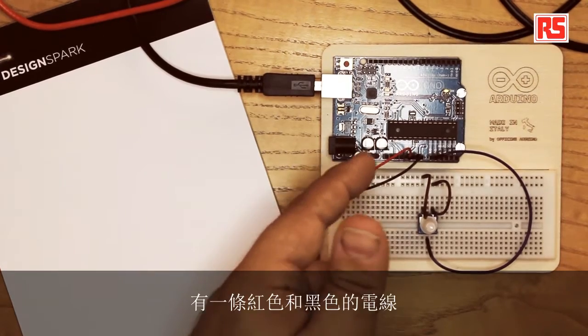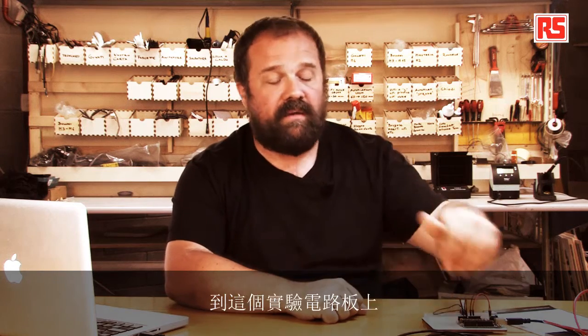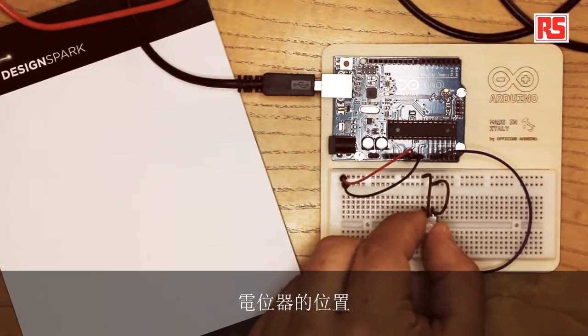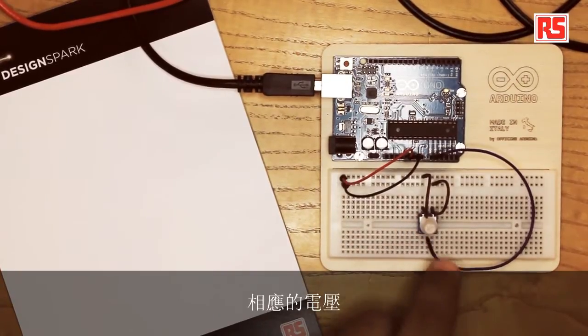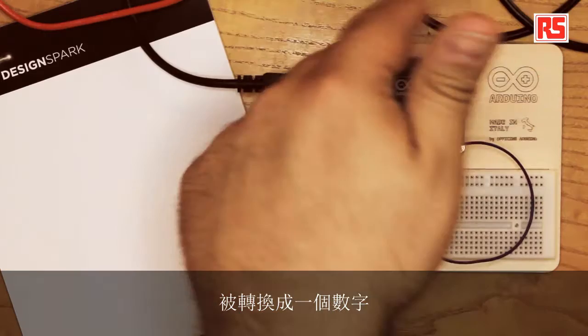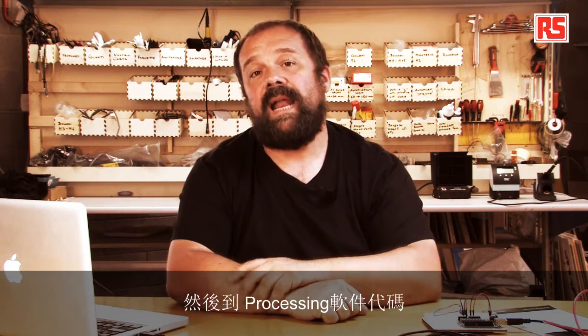And then we have a red and black wire going from those two rails to the 5-volt and ground signals on the board. So when I change the position of the potentiometer, a corresponding voltage comes out of this wire and goes into analog input 0, and that data gets converted into a number that gets sent down the USB cable over to the computer and then to the Processing code.